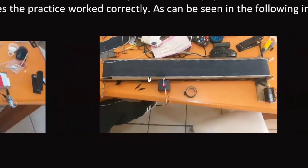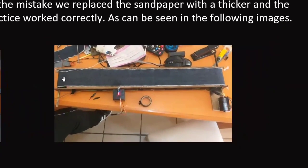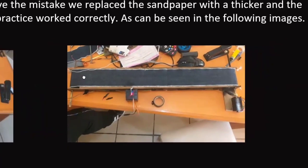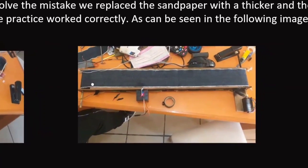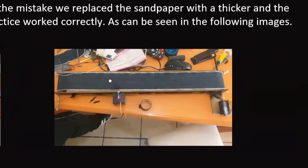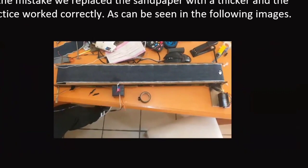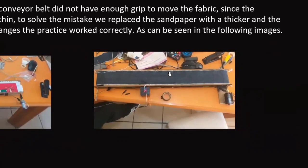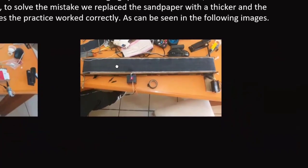So we changed to a thicker sandpaper. Here we can see it. And the fabric we changed to denim, so it grabs better. And with those changes, the conveyor belt works perfectly.